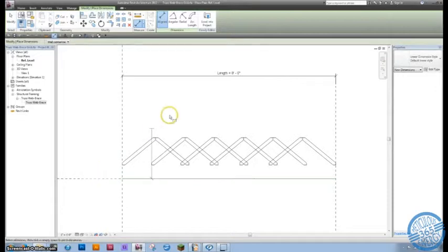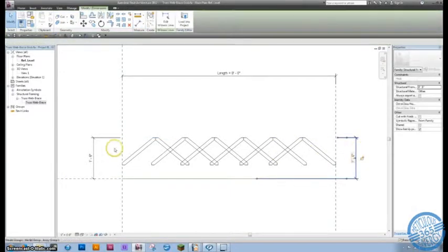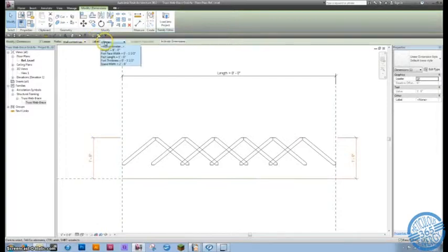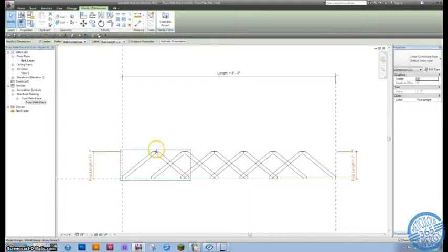So instead, we're going to dimension on this side and then dimension on this side, and provide the value of the height of the element, because the element is defined to be that high and the top of it being that far from this reference will lock it into this position.